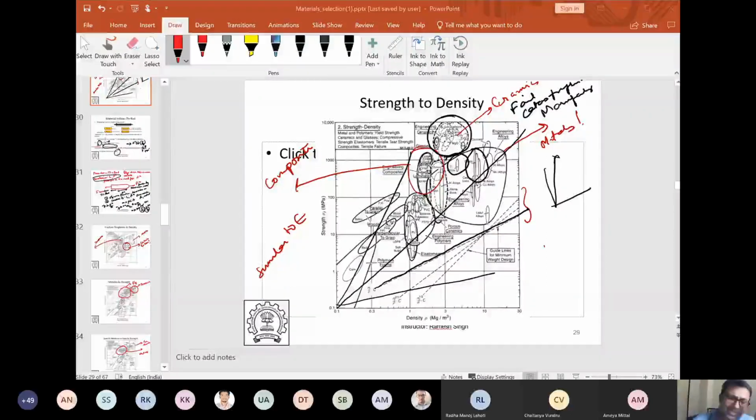But you will go with metals primarily because metals will also have reasonably high E, and it doesn't deform that easily. Composite can take a lot of tension, but there will be some deformation. Your modulus of composite can be close, but then you'll have to pay a lot more money. You can get some composites to serve the purpose, but metals will be much cheaper and you'll get similar E over A ratios. So unless you have something where composite price is validated, you'll go with metals. So you have two choices here, composites and metals, and you will choose metals for this kind of an application, right?